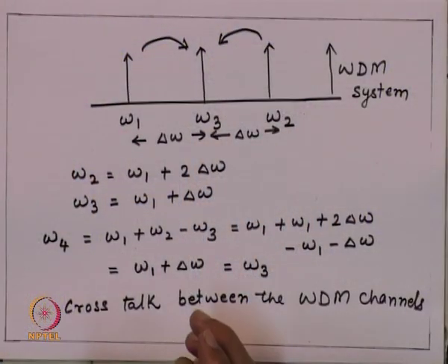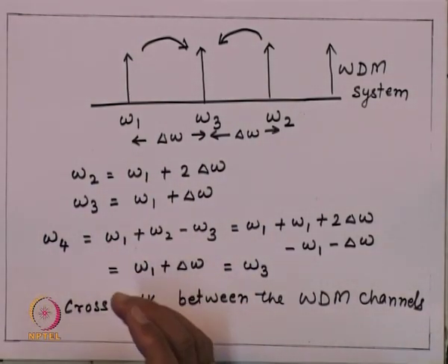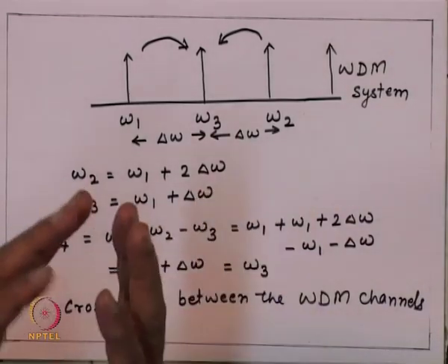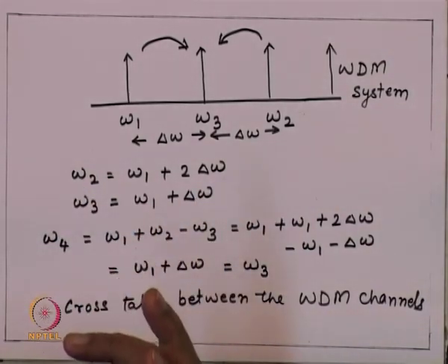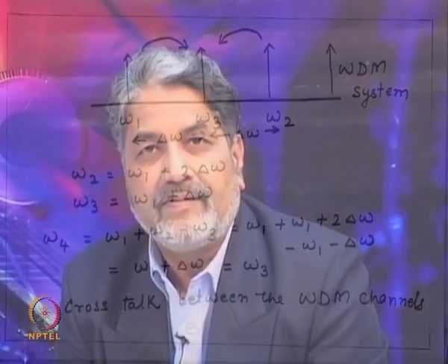But one more thing which can be done, and that is, when the interaction between these things takes place here, it depends upon how these channels are traveling with each other. So, again the efficiency of this four-wave mixing depends upon what is called the interaction factor or the walk off between different channels.